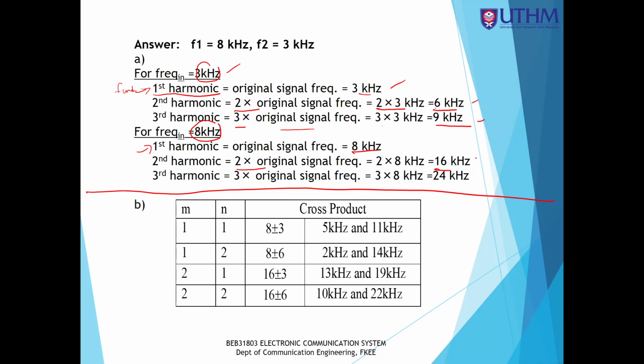These are the locations of the second and third order harmonics. If you draw the frequency spectrum, we have the V sum and difference. Actually we have other frequencies over here, small harmonics produced due to the nonlinear amplification.